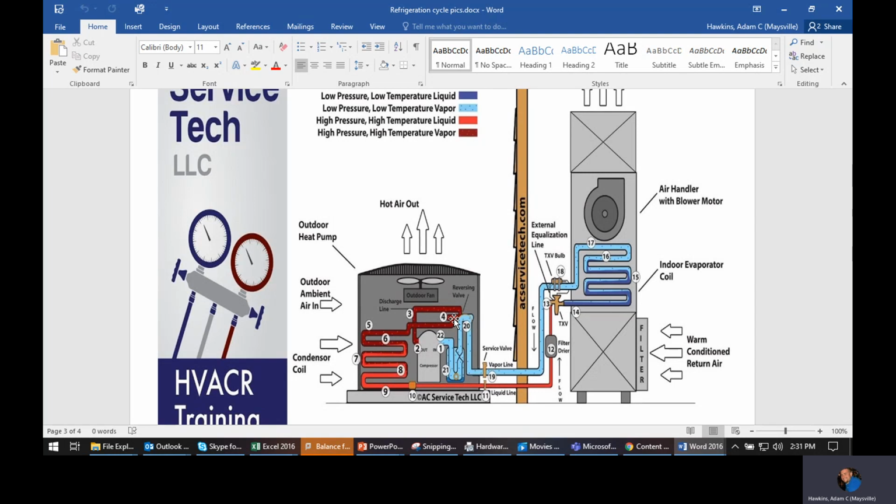So that's another reason why you don't want additional superheat collected in the evaporator, because once you compress, that makes more discharge superheat, which means more of my condenser is going to be used to get rid of that extra superheat. So that means less of my coil is actually going to be used to condense and remove heat from the system. So, like I said before, it's all tied together. If I put more sensible heat in on the evaporator side than I need, I've got to get rid of that on the condenser side. So I want to stay as close to that saturation point as I can, but still make sure that my compressor is safe. So the first step in a condenser is de-superheating.